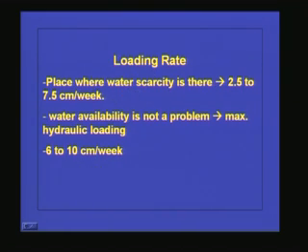And whenever we apply the effluent for irrigation, the loading rate is important. In places where water scarcity is there, we can go for 2.5 to 7.5 centimeters per week, and where water availability is not a problem, then we can go for a maximum hydraulic loading of 6 to 10 centimeters per week. So for the places where water scarcity is not there and water availability is not a problem, you can go for a higher loading.